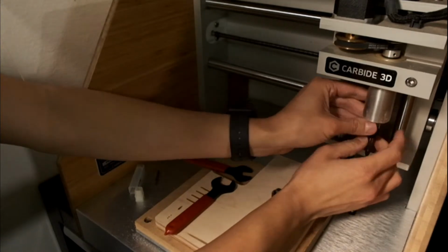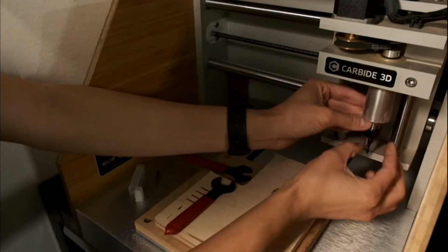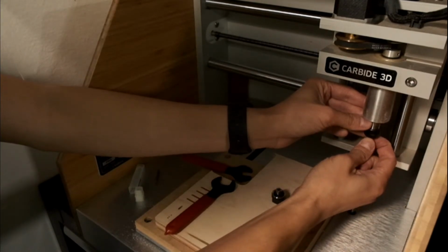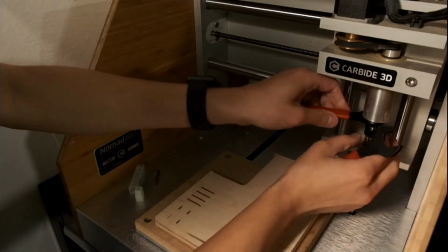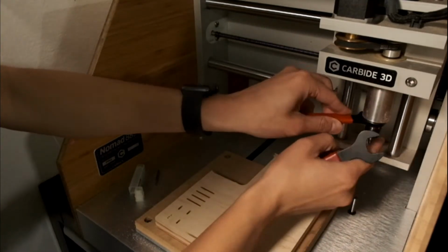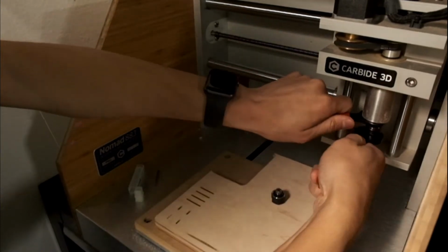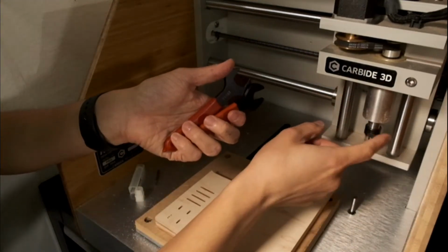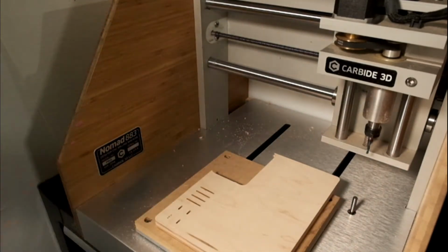Got that a little too tight. As far up as it'll go, and then pull it down about 1 millimeter, and then tighten the end mill. So that way it's floating, it's not butting up against the top of the shaft taper. And that should give you the least amount of run out. So let me clear this junk out.